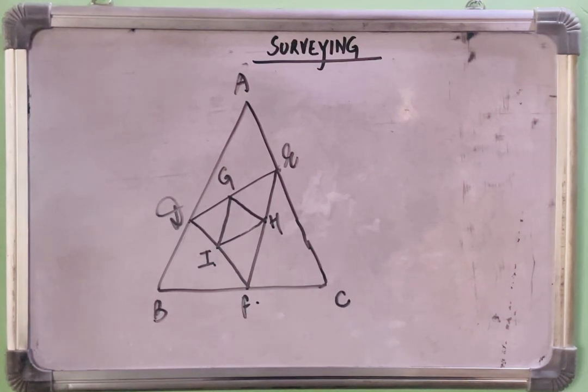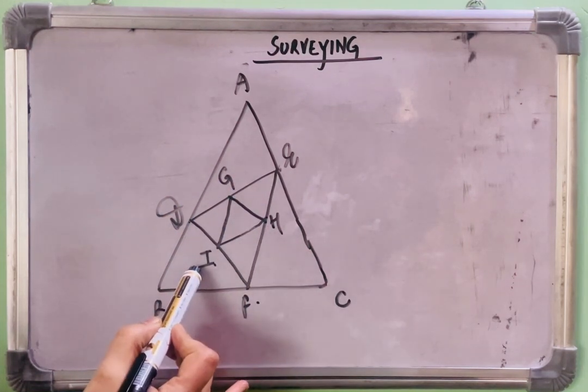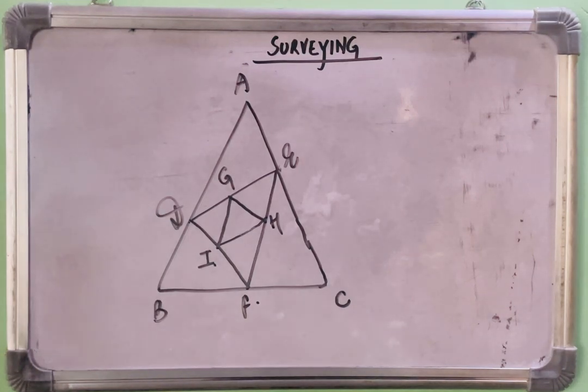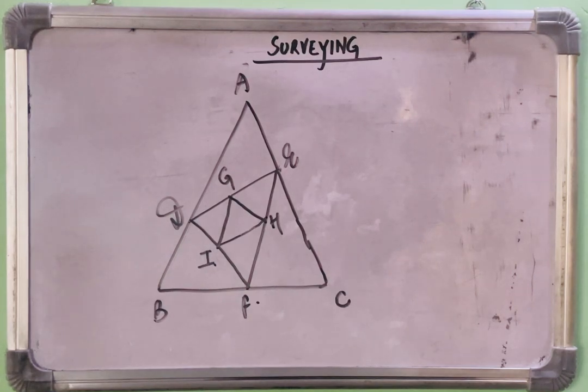For example, if we follow the reverse process of working from part to whole, what will we do first? We'll first establish the position of G, H and I, right? Then we'll form this triangle. Thereafter, from that, we have to establish the location of point D, point E and point F by measuring the distances DE, EF and FD. And after that, we have to establish the points A, B and C. And it's quite likely that the position of the points A, B, C as obtained by this process will be less accurate than that working from whole to part.